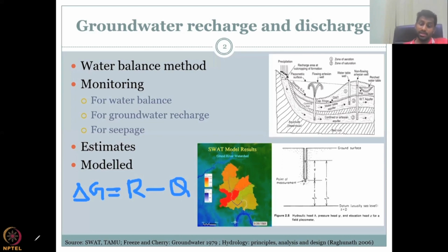These are the estimates that you can put with the back of the envelope. And even the R, which is your rainfall, which you need data, or every month you have a statistical model to predict the data. But Q, most probably, they do estimates. If you know, for example, it is a cement road. If you know, for example, it is a forest, you know that 80% of the water will run off. The remaining 20% will go in. So those kind of percentages are estimates based on previous field work from different locations.